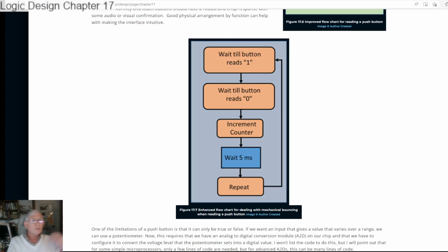And you can find these things out by using fancy circuits and oscilloscopes and looking at your buttons. And not only that, but unfortunately, as your device ages, your buttons will get a little dirtier over time, and the bouncing will get worse. Brand new clean buttons might not bounce at all or very little, and then later on they're going to bounce like crazy.